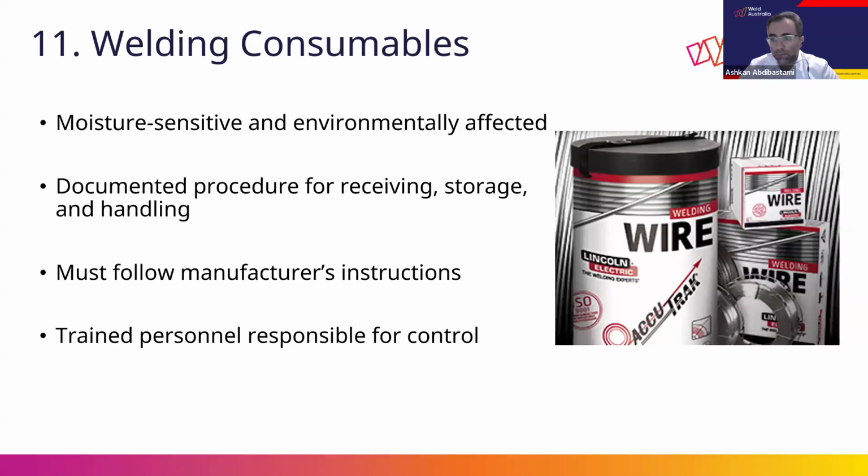And the other thing is, if, for example, you have WPS to ASME 9 or D1.1, during the audit we need to verify a couple of WPS and PQRs and a couple of welder qualifications to that standard, to make sure the fabricator is competent and complying with the requirements of that standard, in order to list that standard in your scope of certification.